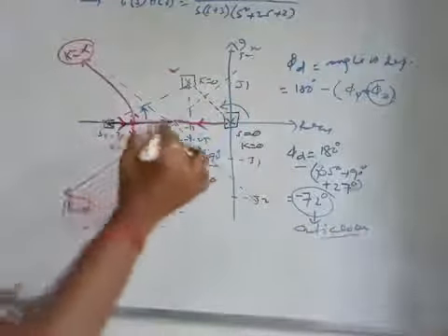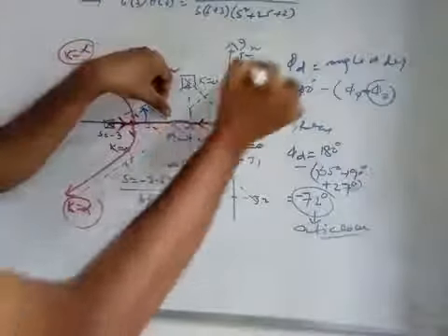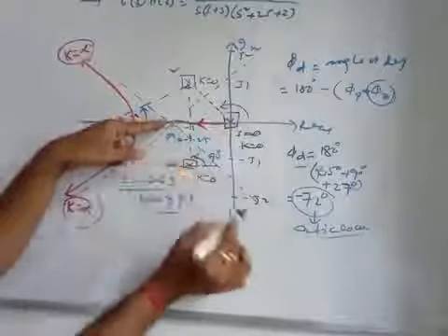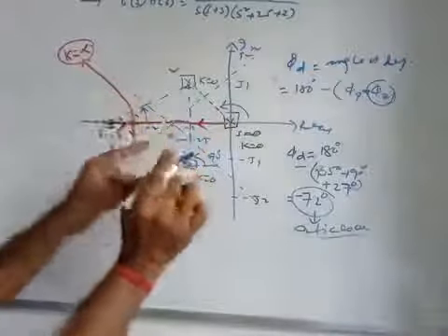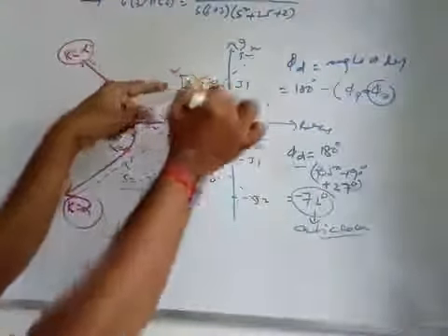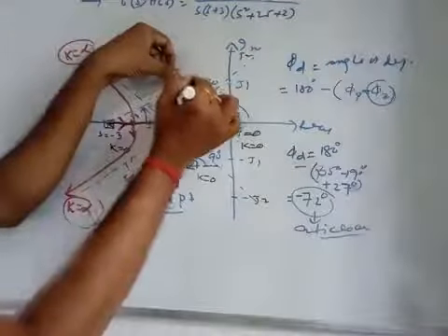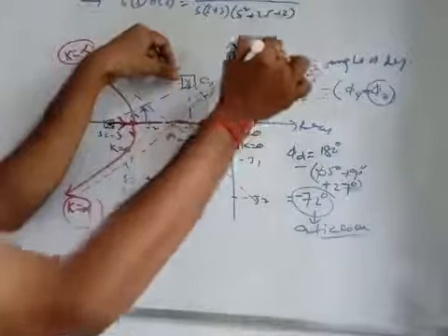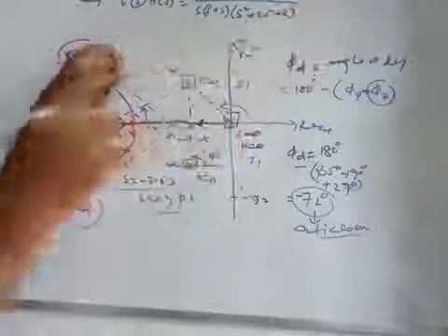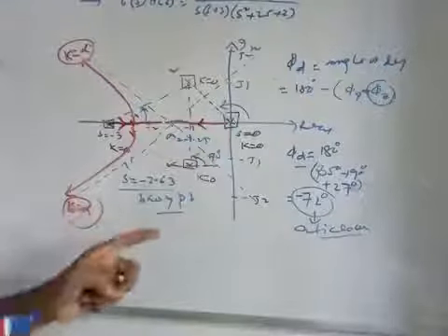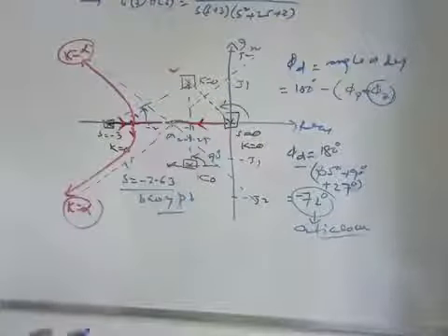And the second thing is that this is one asymptote which is going in this direction, and this is another asymptote going in this direction. So there is a possibility of intersection with the root locus branch which will originate from this pole. Maybe this pole will originate like this and go in these directions. In that case, we have to find the points of intersection with the imaginary axis by using the Routh array. Okay, we will do it.